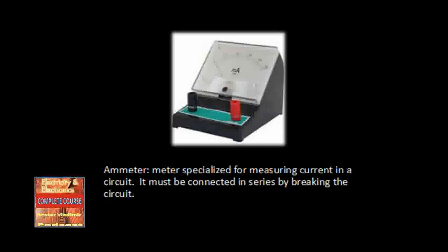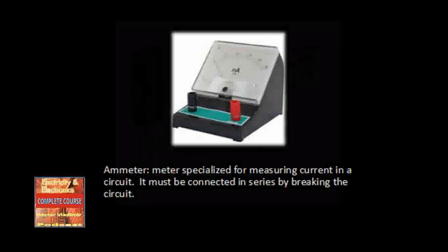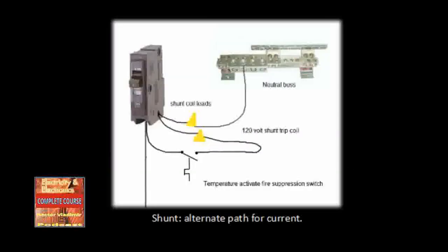2.2. Ammeter. An ammeter measures electrical current in a circuit. The ammeter will usually measure in amperes, milliamperes, or microamperes, depending on the scale design of the instrument. The coil in the meter movement of an ammeter is wound with many turns of fine wire. If a large current is allowed to flow through this coil, the ammeter will quickly burn out.